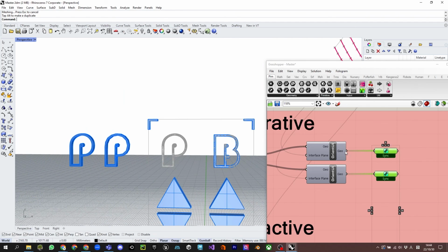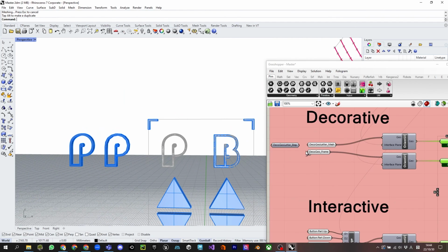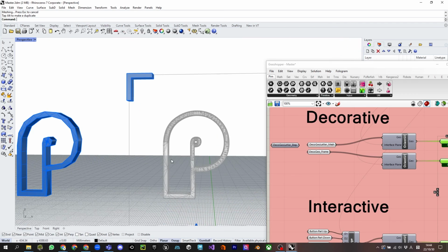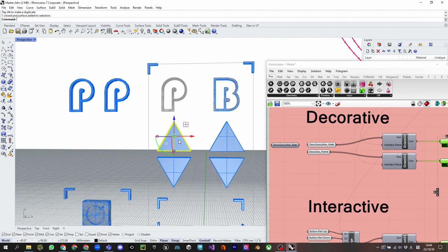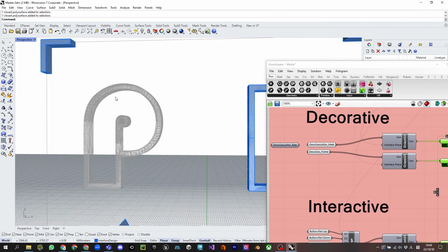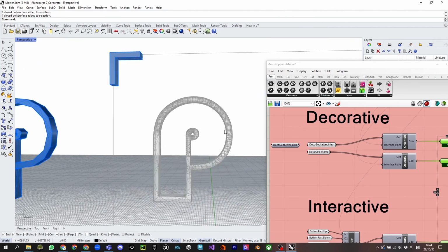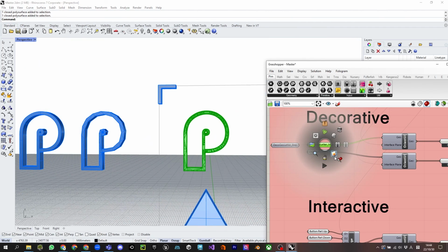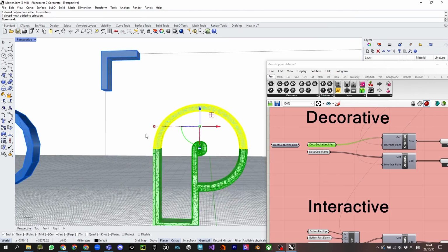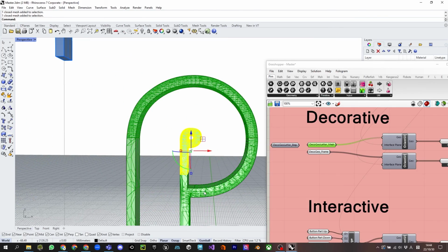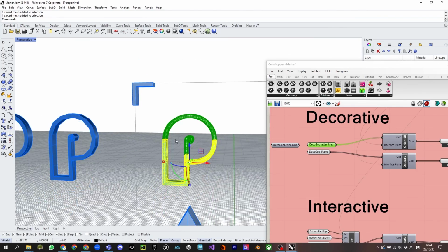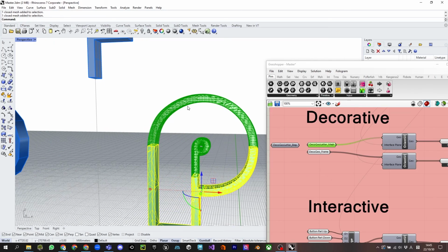So just before you give it to HoloLens, if you have a lot of curvature or something that is not as simple geometry as these ones, please make them into meshes. So for this case, let me bake this one and show you. I had to separate this into a few chunks in order to make them smooth and clean.